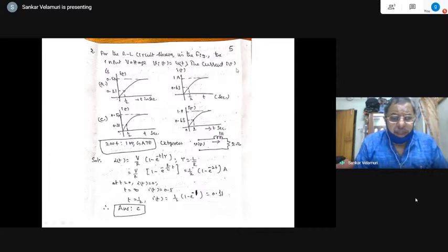So these two are ruled out. The steady state current is equal to half ampere, because that is well known: unit step function, 1 volt, 1 divided by 2 is half. So this is half ampere, 0.5 amperes. Sorry, I did not write the unit. Okay, so at t equal to infinity its value is equal to half ampere.